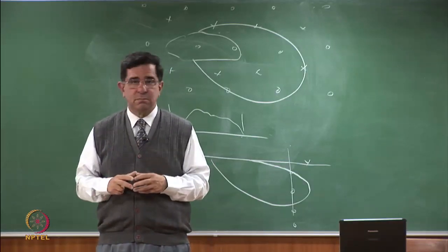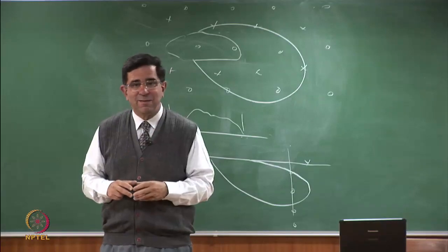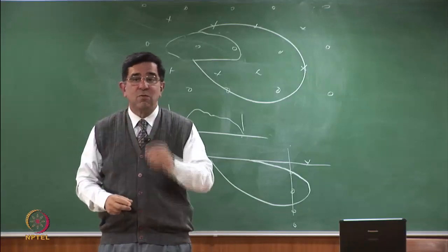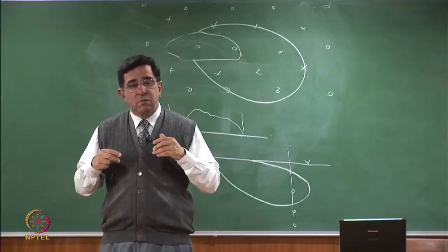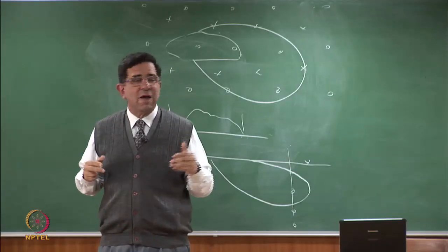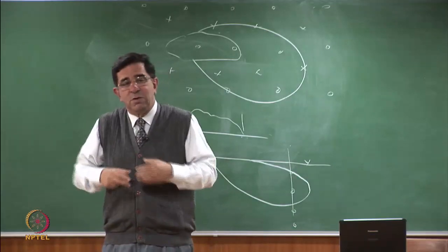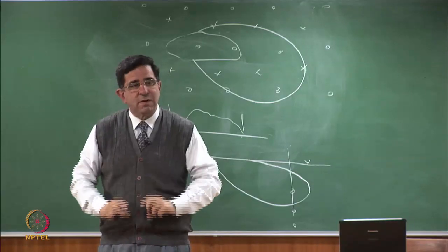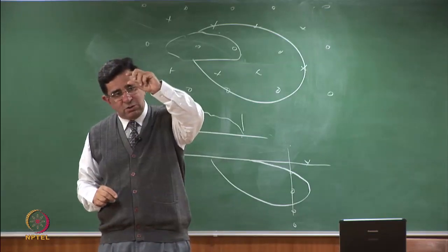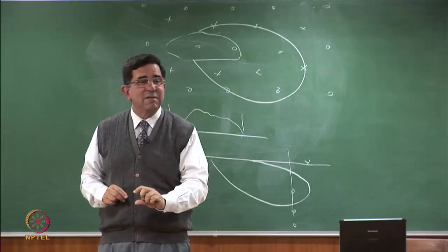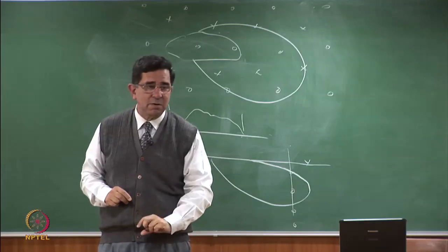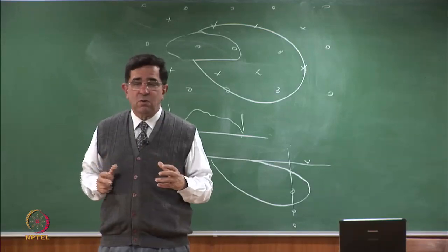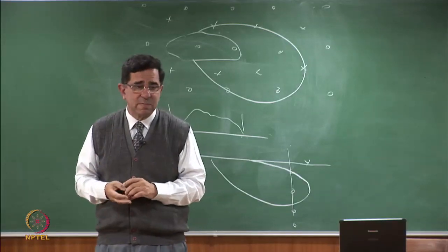The multi-port groundwater well is the cutting edge for taking samples in one borehole from different depths, whether you monitor it once a month. You see, the groundwater doesn't travel very fast, I've already told you. So you may monitor groundwater only once a month, but at least you are able to pick up the samples from the different depths and you know there is no contamination at the top, but you are getting a slight increase in reading at mid depth and there is no contamination at the bottom. And with these devices you can monitor your old and new landfills.